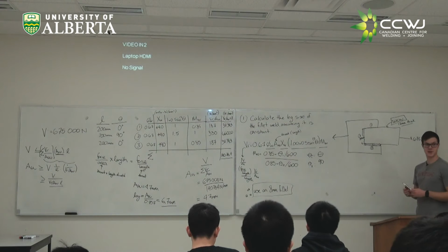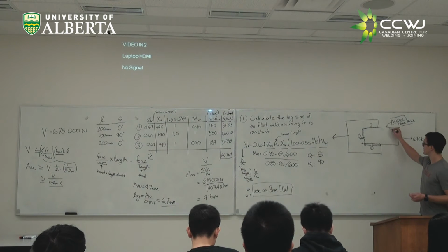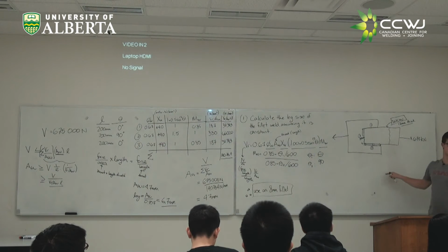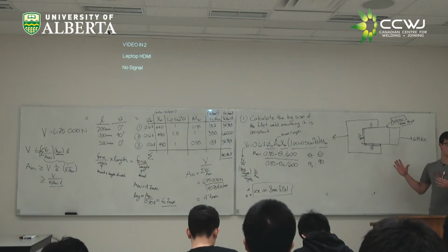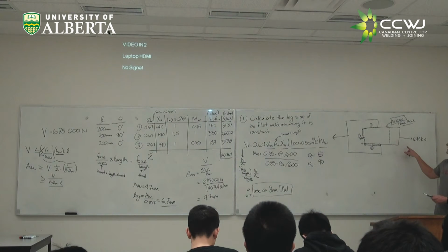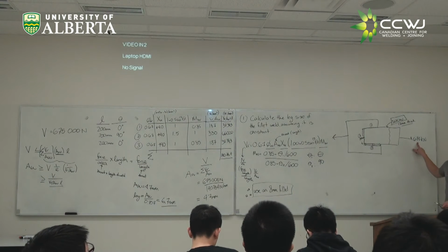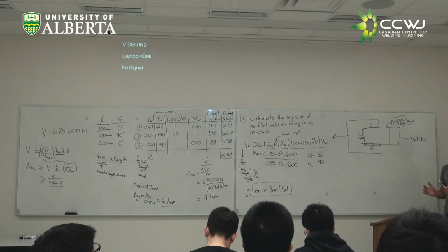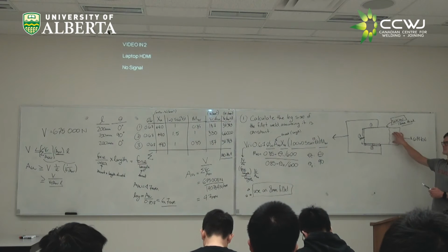One other thing we didn't do here, but in practice, you would probably want to do if you were designing this, and I think we talked about last class how you do that. We didn't check to make sure that we're not going to fail through the section. Now, we're designing the welds. We're going to focus on the formula for designing the welds, but this is part of a structure. We're kind of taking it for granted that if we have a 12 millimeter plate, we've been given the dimension here, we're assuming it's not going to fail when we put 675 kilonewtons on it. We're assuming whoever gave us this problem designed this structure so that our weld was what we had to worry about. This wasn't going to fail.